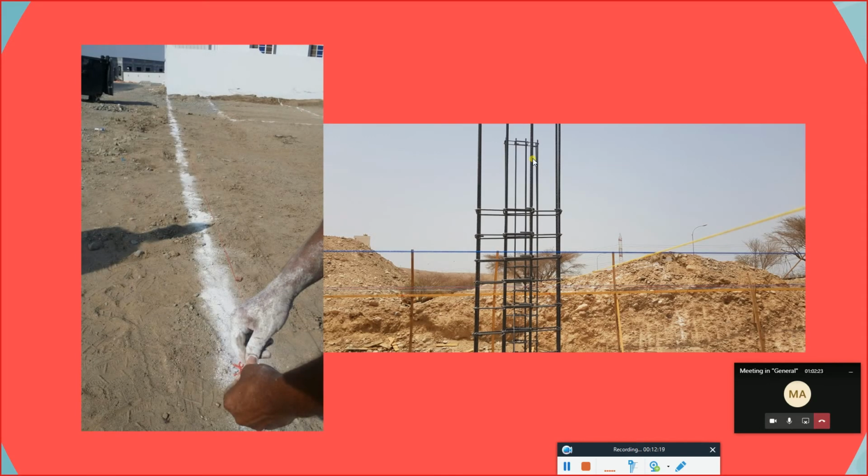Okay, threads, which are like small strings or ropes. So if you can see a red one here, they are representing our grid lines. Whatever grids you are seeing in your drawing, we are going to use the threads, the string or rope, to specify the grid's position. Now whenever grid A, for example, intersects with grid 10, and there is a position of a column, I'll know that this column is situated in this particular point.